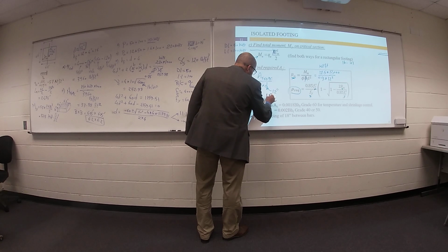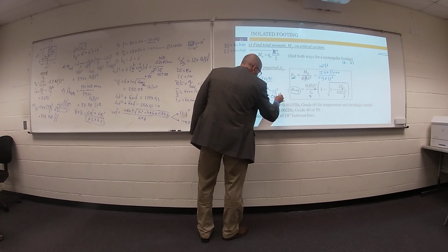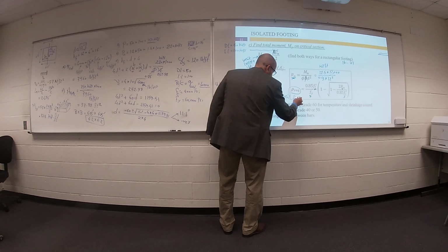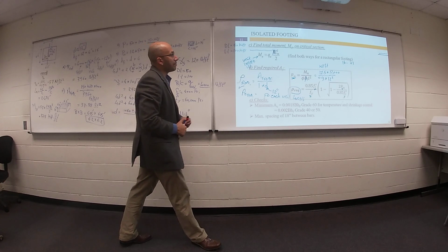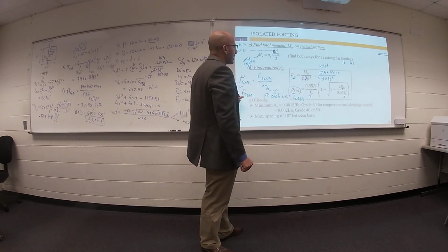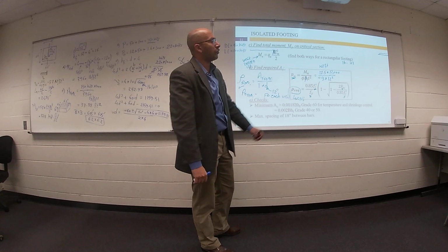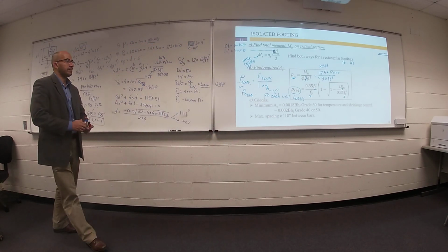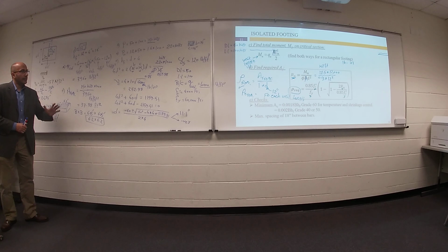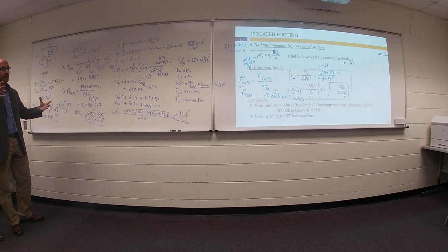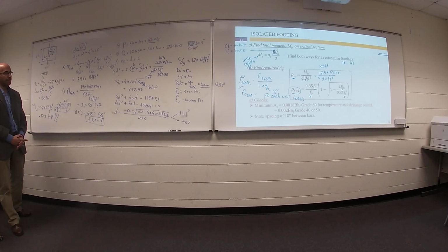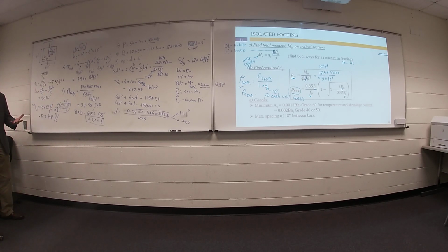This area of steel is for each unit length, because I removed this B and this B. If you keep this B and this B, your area of steel will be for the total length of your footing. Both of them work. A lot of calculations, and this is only for one footing. If you design the second footing and we have overlaps, we need to remove everything and design a new footing, a combined footing. But we need to understand the concept behind it.